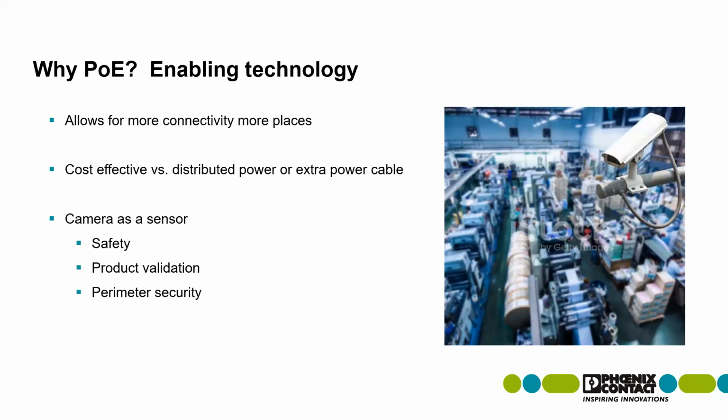And please don't think that it's just some person sitting there looking at a screen, waiting to see somebody reach in and do something. Cameras more and more are now able to feed what we would consider industrial data inputs, if you will, to PLCs, and those PLCs, or those IO blocks, are able to recognize, oh, the camera saw something that looked like a person. This camera is monitoring a place where a person should not be. Therefore, I'm going to trigger a stop.